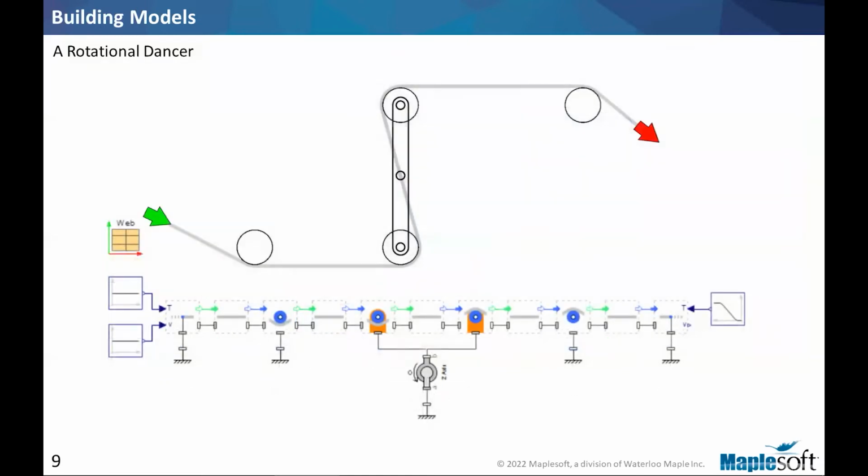So just to finish this example, we have the model. You can see that the arrangement of icon in an actual model is one stream. So with the help of parameter values, we tell MapleSim where everything is. We don't need to actually put them relative to our layout. Now we want to add 2 more idlers to add a little bit of accumulation or storage in this dancer as we have it like this.